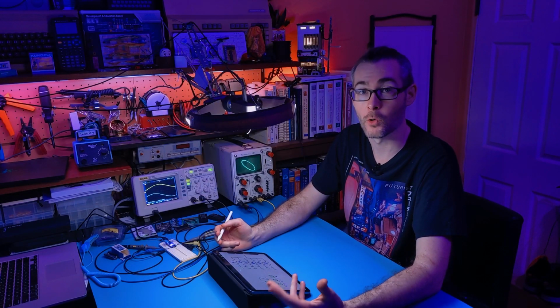PWM works great for LEDs and motors where the value doesn't need to change too quickly and the highs and lows can be averaged out. Vector graphics is just not one of these cases, since we need to be able to update the value extremely quickly and without any noise in order to create a stable picture. What we need is a fast digital to analog converter, or DAC.